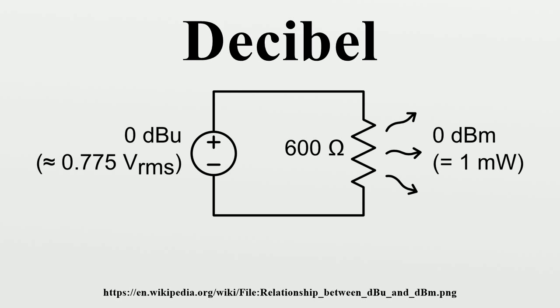Similarly, an increase of 3 decibels implies an increase in voltage by a factor of approximately square root 2, or about 1.41. An increase of 6 decibels corresponds to approximately 4 times the power and twice the voltage, and so on. In exact terms, the power ratio is 10^(6/10), or about 3.9811, a relative error of about 0.5%.